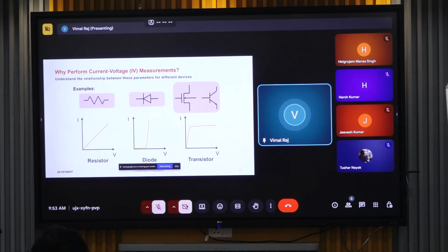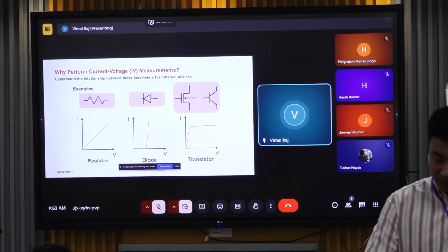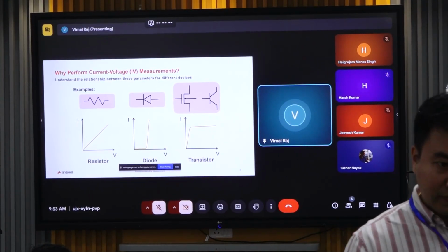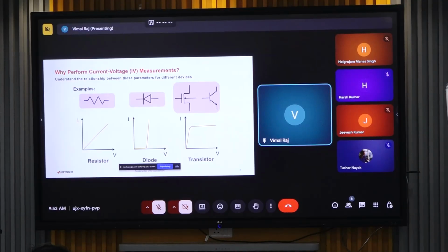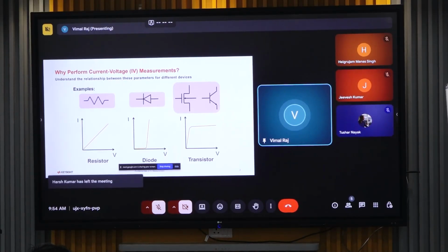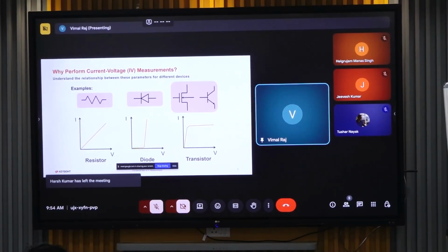In our equipment, we normally set the sample rate, the sample speed. Every 50 microseconds or 20 microseconds, we can fix the voltage and measure the current. Like that, we can get a clear, highly accurate curve with more resolution.